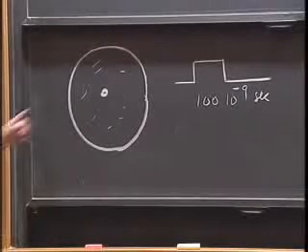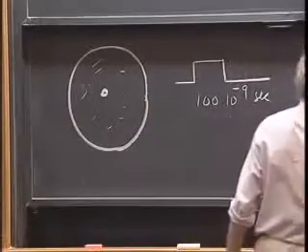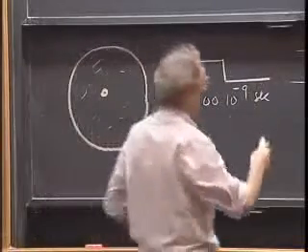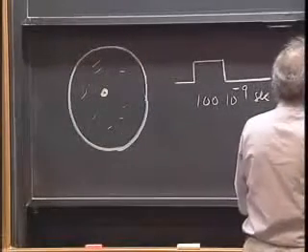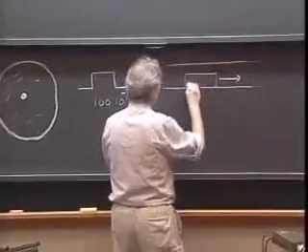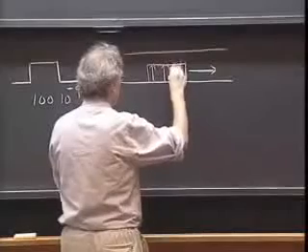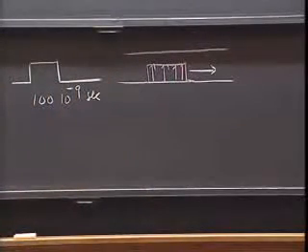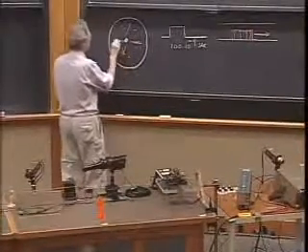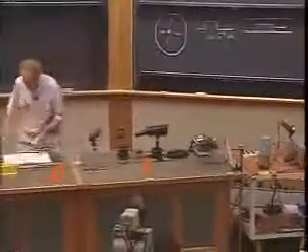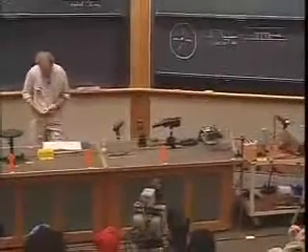In other words, if you look at the wire from the side, so here is the wire, and here is the shell, just take a cross-section here so you see only that shell, then as the voltage pulse moves in this direction, then you will see locally between the outer conductor and the inner conductor, locally you will see that E field, and it goes to 0 here and here. And that marches then with a certain speed along the wire. And so as that pulse passes, there will be an E field like this. But when there is no pulse, there is no E field between this and that. So in that sense, it's sort of similar to this transmission line, except the geometry is different here. It is a coaxial cable.